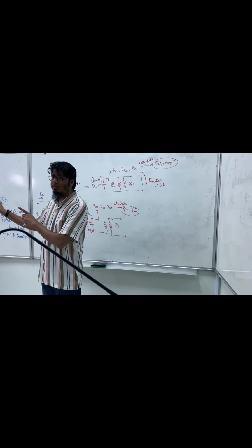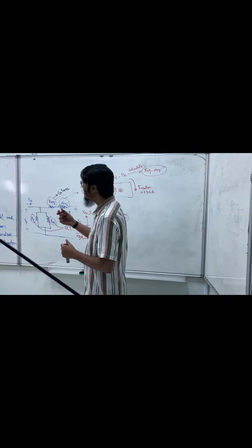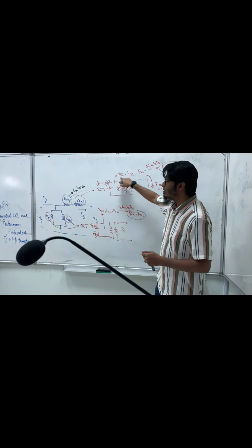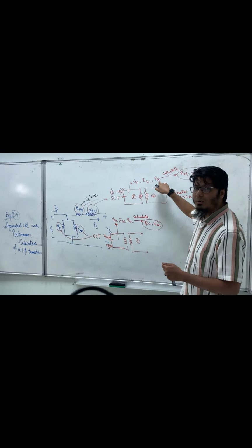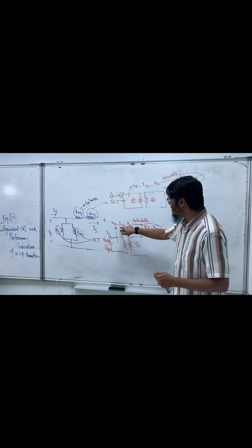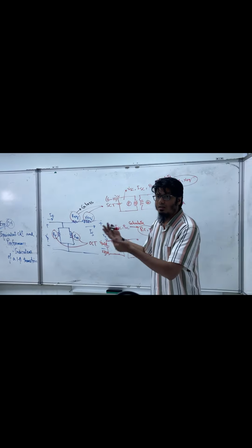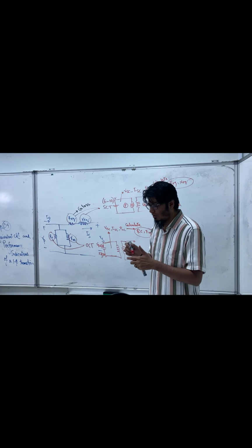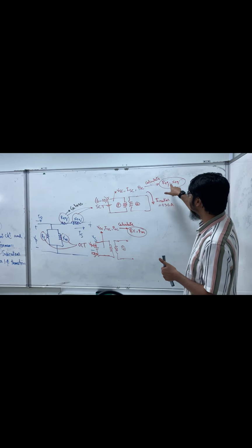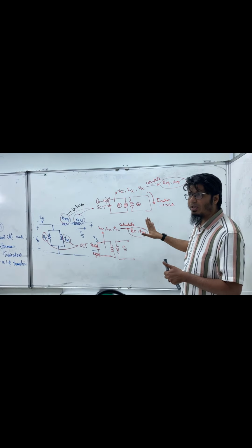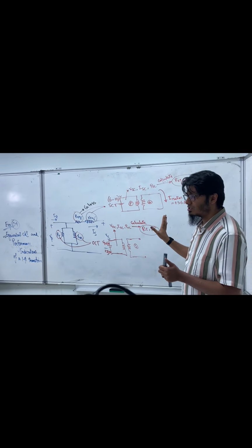Not in the lab, because we will take only these values: short circuit voltage, current and power, and open circuit voltage, current and power. We will take them and we'll leave. You understand? Later you will do the calculation using the calculator. You will calculate the R equivalent, X equivalent, and so on. So this is the open circuit test and short circuit test.